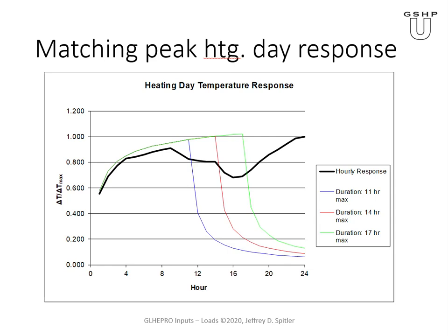Okay, so what the tool is going to do is it has a model built in, and it computes the temperature response both for the actual hourly load for that peak day and for a peak day that has zero load part of the time and then has the peak load. I say zero load part of the time. It's a little more complicated than that.